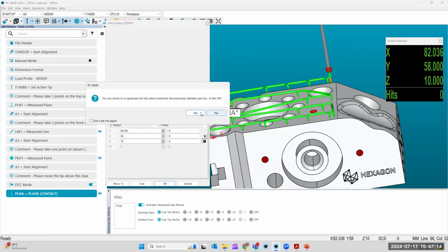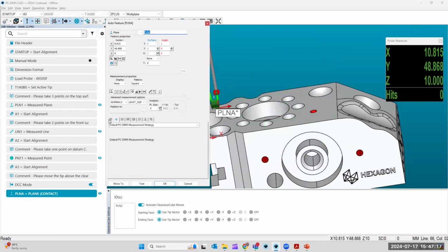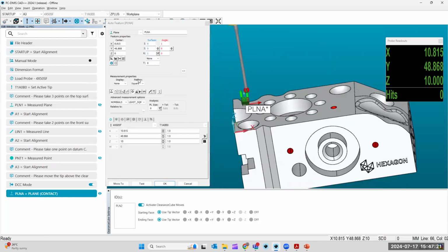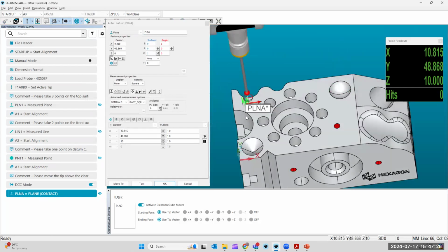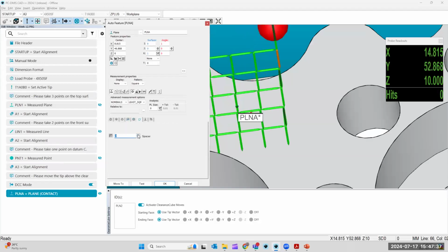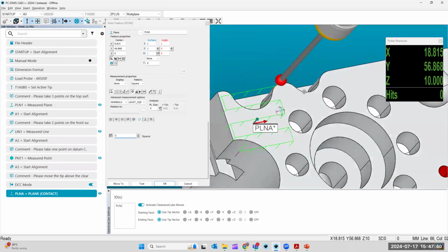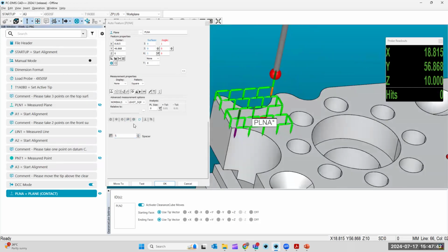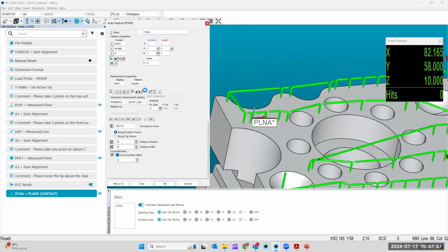And I think that covers everything in our, what's this one? Position probe. So that one's kind of unimportant. I have somehow turned off my void detection though. See how it went back to the grid? If I went and looked at my grid, the spacer would have to be increased to change the grid size. But now the grid is half touching air and not touching the part. That's why I like void detection. It's so much more powerful with void detection turned on.